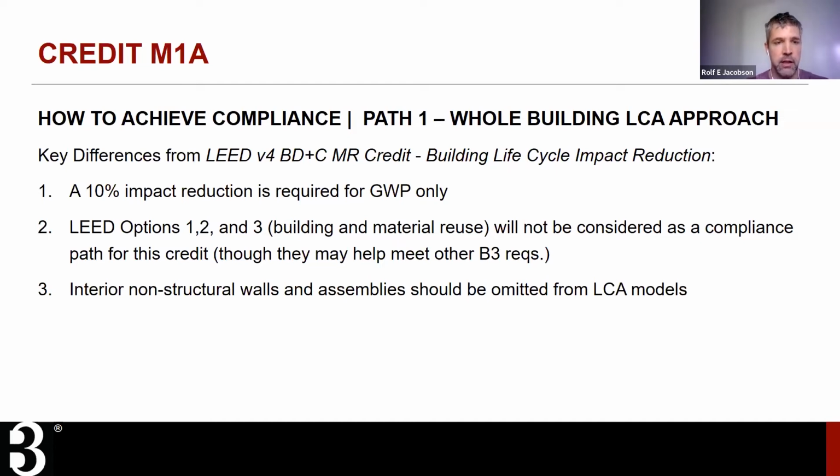And finally, I think there is a difference still between the LEED whole building LCA models and ours, in that we do not want to see the interior partition walls in our LCA models, and I think LEED will allow those. Sometimes it's just more work to include those, unless you've got a BIM model, and then hopefully it's easy to strip those out.